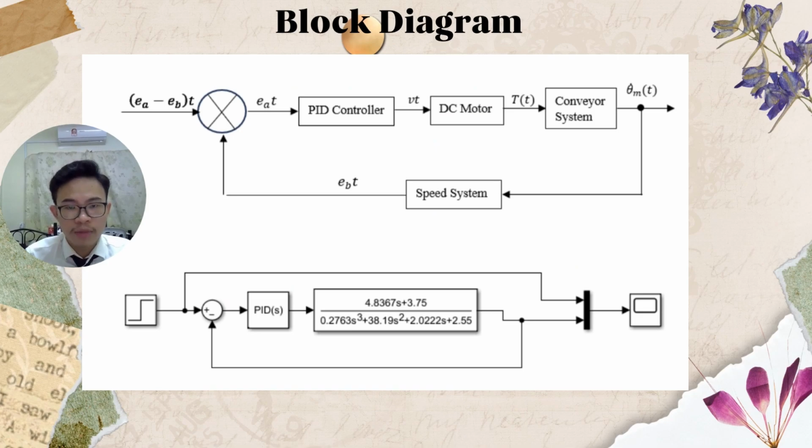The block diagrams will be constructed both manually and in MATLAB. The top figure is the block diagram constructed manually, and the bottom figure is the block diagram constructed in MATLAB. As we can see, the step input is connected to the summing point, then to the PID controller, then to the transfer function, and then to the output. So that's all for the theoretical calculations and analytical procedure.